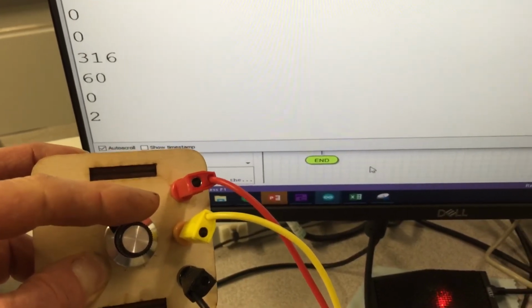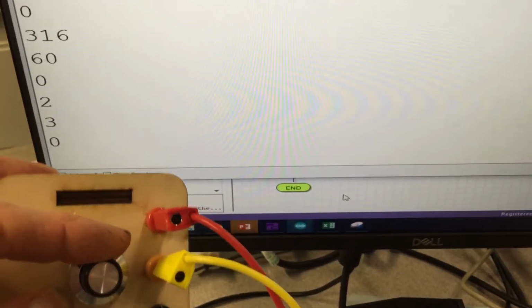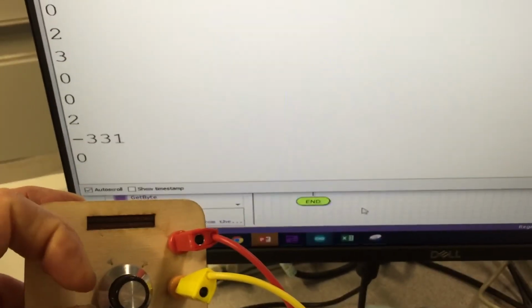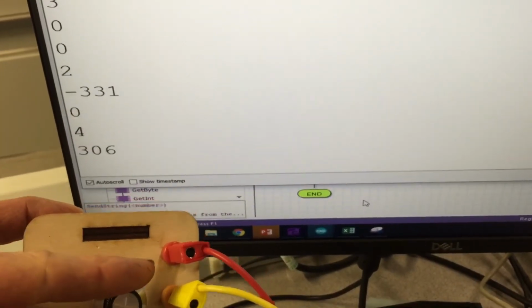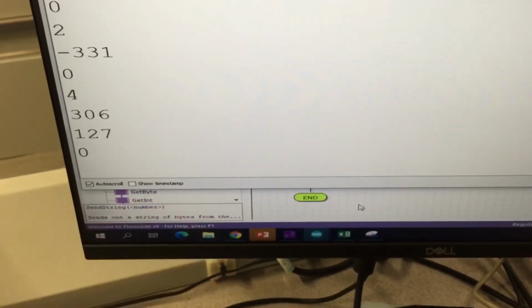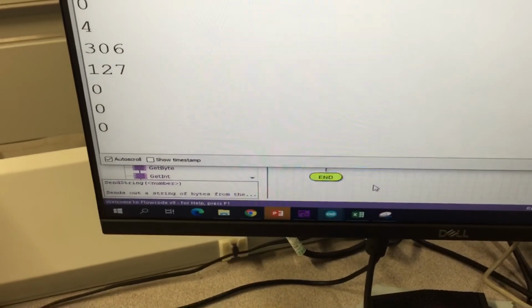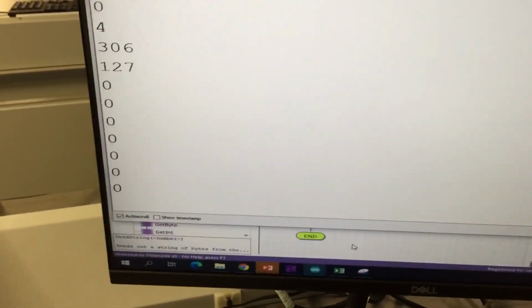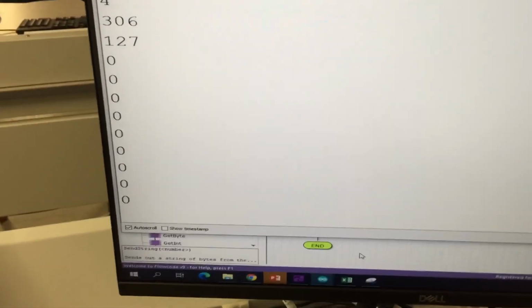Now it's not calibrated to anything. We can always worry about calibration later. It's just simply telling me how I can find out what the speed of something is. So that's quite handy for speed of rotation. It doesn't have to be rotation, it could be translation as well. We could be reading a wheel sensor so we know the velocity of a car, for example.